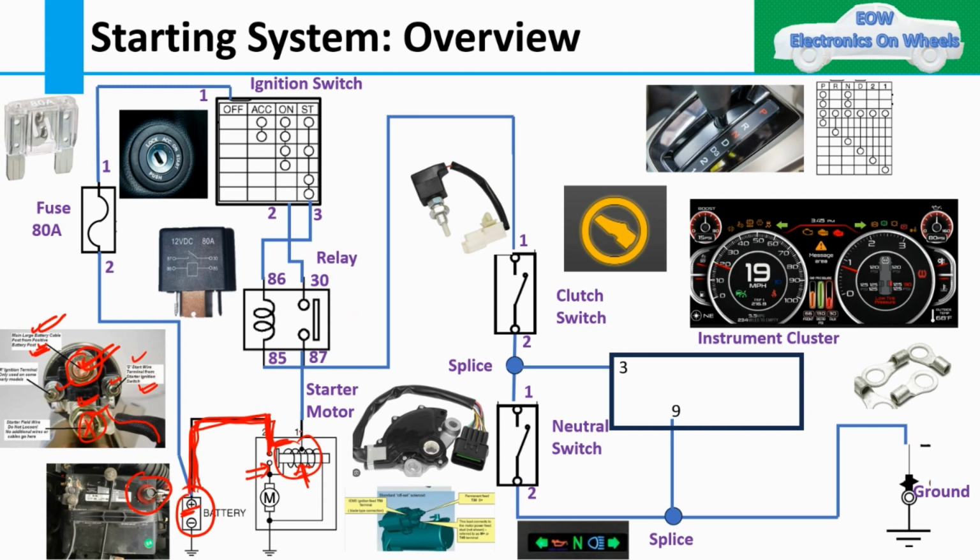This is the start ignition switch for the solenoid. For the starter relay, this is my relay, which we call the starter relay. I hope the battery and these two terminals are clear. This second terminal is connected to the battery positive, which goes to the starter motor to give the current to the starter motor most of the time. Then this first terminal goes from the solenoid to this particular relay, that is the starter relay. We will see what its function is. Till here we are good.